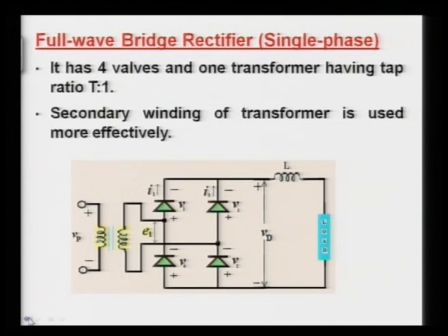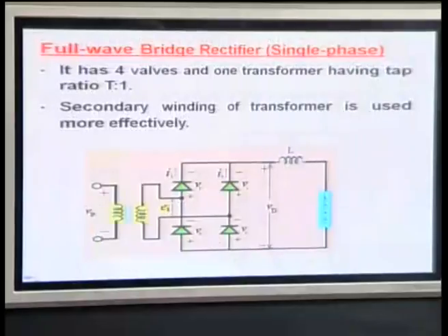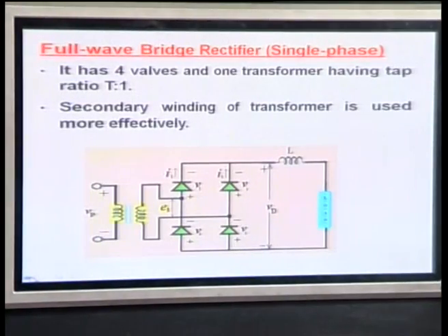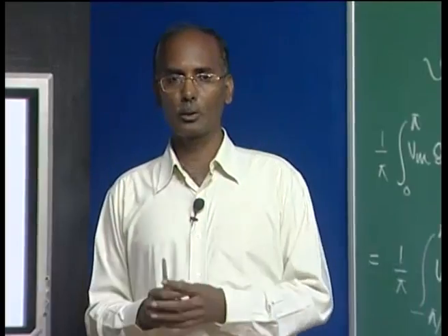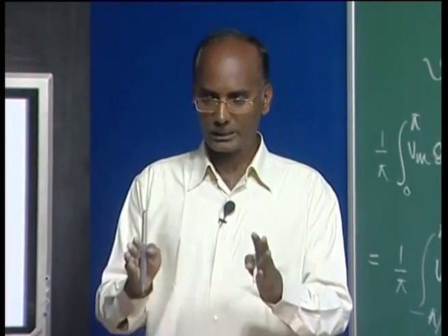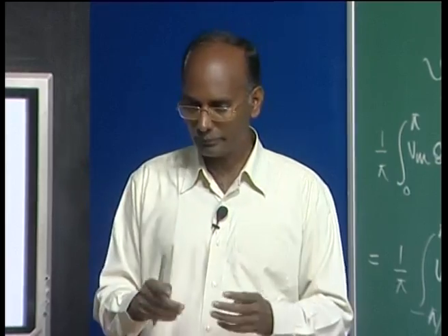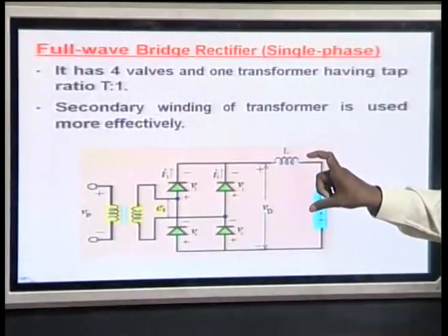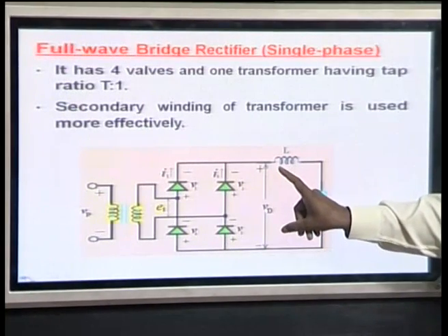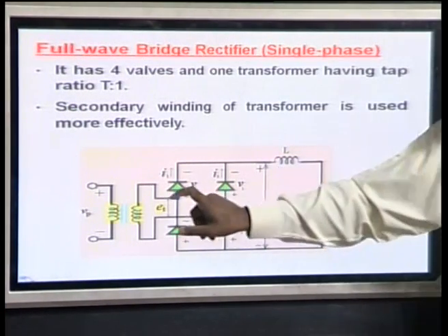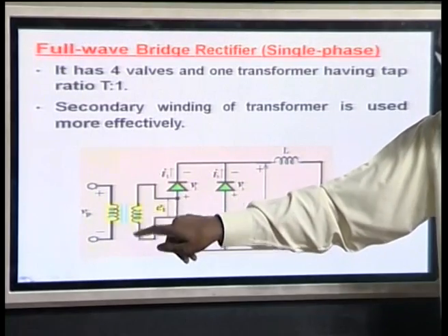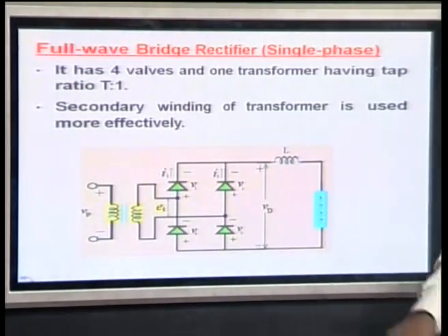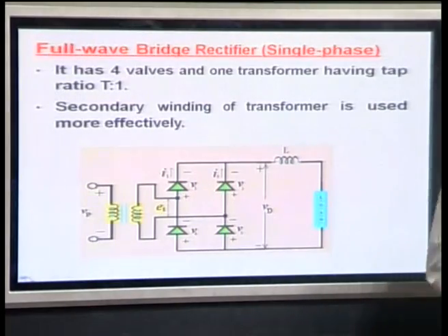This is also a consideration when analyzing any circuit: what is the utilization factor of the transformer. Later, when we analyze the DC rectifier and what the optimal configuration should be, our main considerations are that we should have the maximum output voltage for the same given sinusoidal EMF, the transformer must be utilized properly, and the peak inverse voltage of the valve should be the minimum.